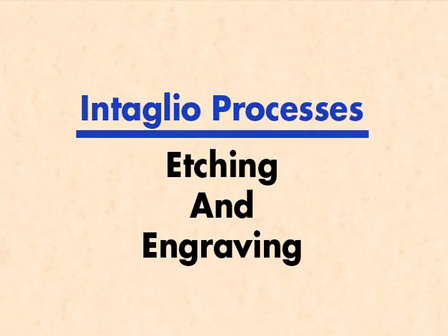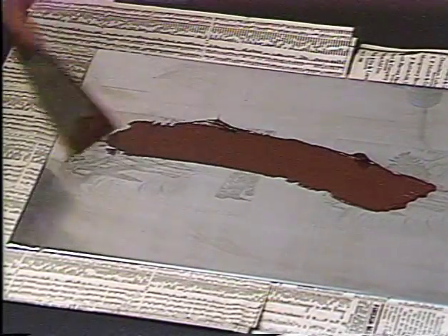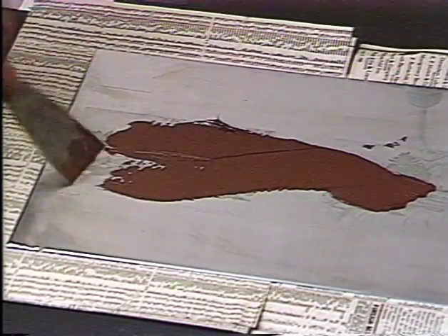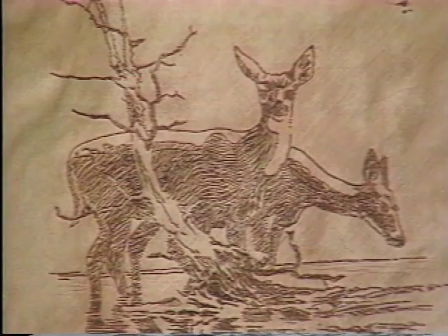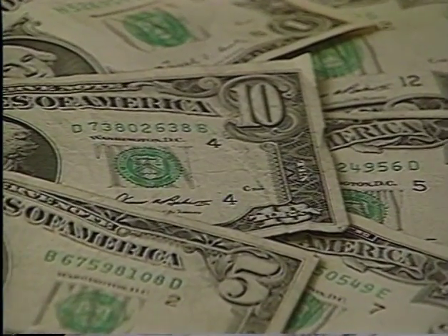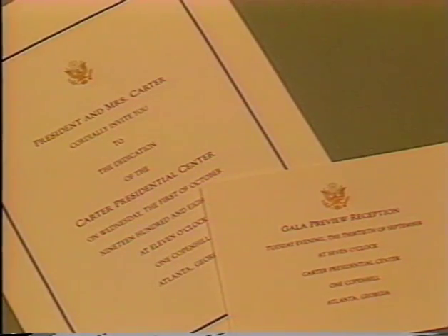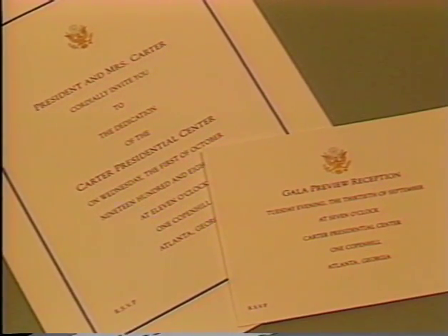Simple forms of intaglio are etchings and engravings. Lines may be scratched, engraved, or etched in plastic or metal. A buttery ink is applied to the lines, and the surface of the plate is cleaned. A print is made using pressure. Art prints, paper money, and other high-quality engraved printing utilize this method of intaglio printing.